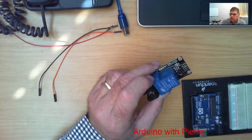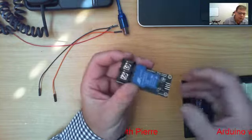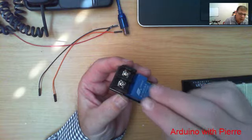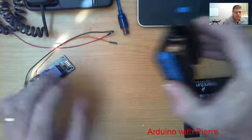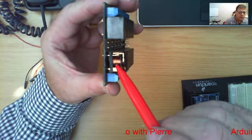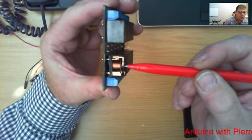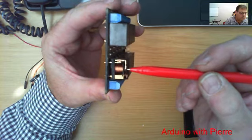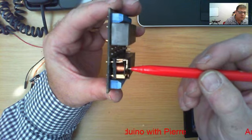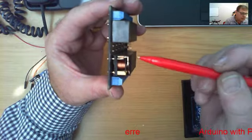You also get solid state relays. Now the difference between a normal relay like this one and the solid state one is this one's got physical contacts where the contact will open and close. And I've cut open one of these relays to just show you that. There you can see the coil that's energized, and it will then pull that magnetic part towards it, and it will open or close this normally open, normally closed switch here on the side. So this is basically the inside of a normal relay with contacts.